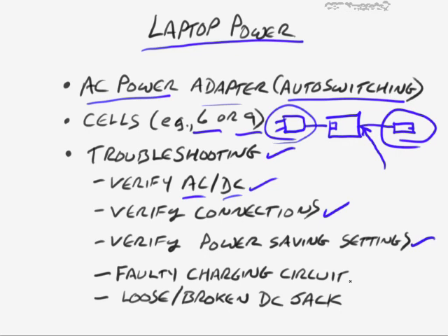And then you're also going to want to check for a faulty charging circuit potentially. If everything else is fine, the power cord's fine, you're getting a little light. Sometimes they have a little light on here that lights up to identify that the power is flowing through it and so on. It's not frayed here. If everything's fine and you tested this with your digital multimeter, but the laptop still doesn't charge, that could indicate two things. Number one, a faulty charging circuit. I would know about this for exam purposes because it's well within our exam objectives.